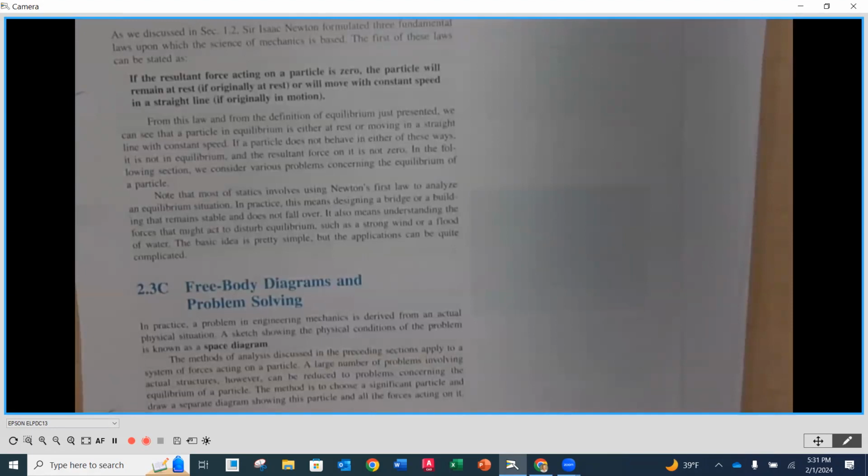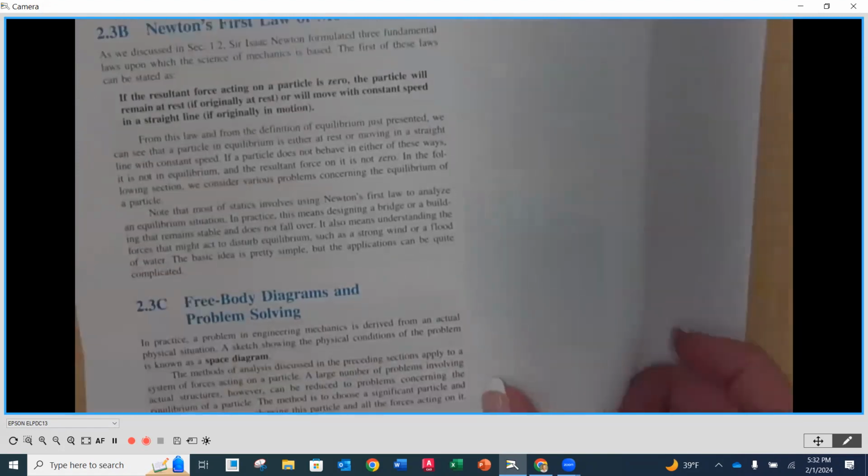And then make sure that you have all of the information in the format you need it to be. If it's a force, it has to be aligned with a vector. If it's a force, we also have to have an angle or solve for the angle to fully define it, and make sure that all of our labels are there. As we continue to add on to this subject, there will be standard ways that we show certain things like pin reactions or roller reactions or cantilever beams. Those will come a little bit later, but right now we'll get an introduction to free body diagrams.